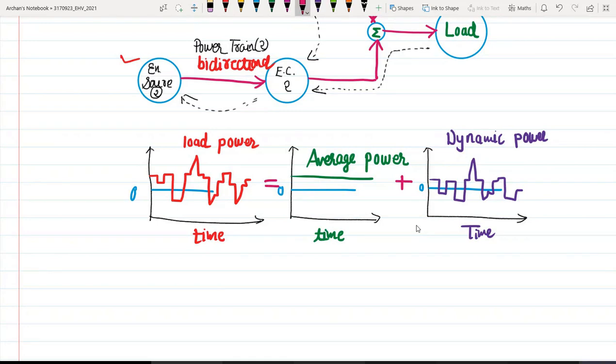It means that the energy source of the dynamic powertrain does not lose energy capacity at the end of the driving cycle. It functions only as a power damper. Okay? In a hybrid vehicle, steady power may be provided by an IC engine, a Stirling engine, a fuel cell, etc. The IC engine or the fuel cell can be much smaller than that in a single powertrain design, because the dynamic power is taken by the dynamic power source and can then operate steadily in its most efficient region.